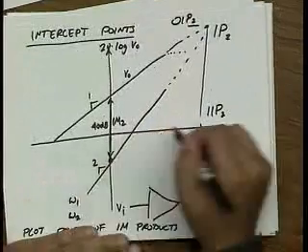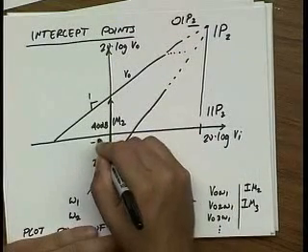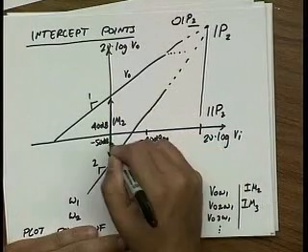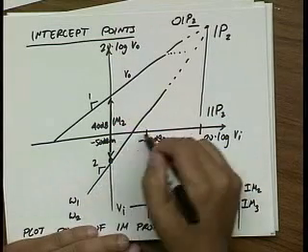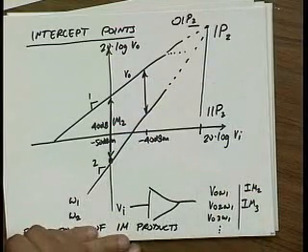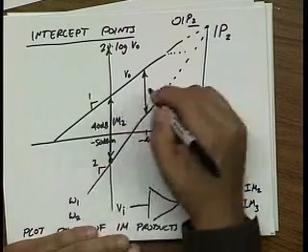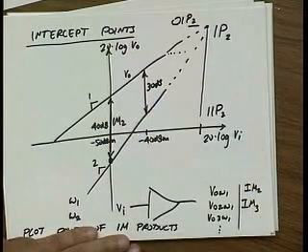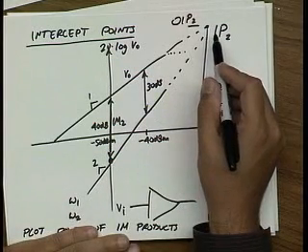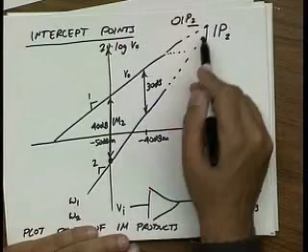What's interesting is that as I change, let's say, my input power, for instance, this corresponds to minus 50 dBm input power. Let's say I go to minus 40 dBm. Say it's on a dBm scale. Well, that means that my IM2 changes by also 10 dB. So if I change the input power by 10 dB, the IM2 will also change by 10 dB. So here, instead of 40 dB, it'll be 30 dB. And so if you know the IM2 at any given point, it's very easy to calculate how far you need to go to get to the intercept. If I'm at 40 dB here, right, 40 dB difference, I just move 40 dB forward, and boom, I have the intercept point, right?